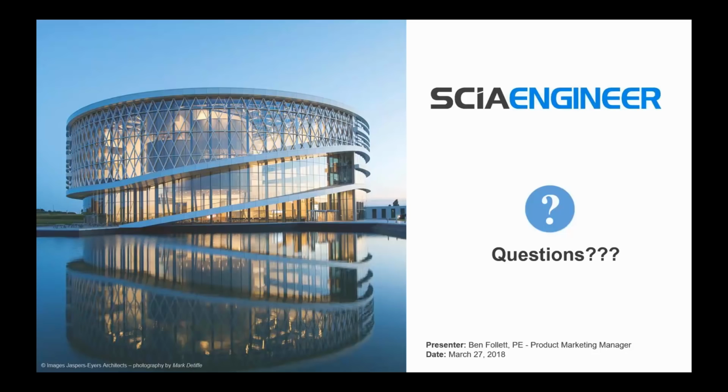Let's see what else. There are some questions about buckling. In this particular case, we have the 1D members that act as the stiffeners. Buckling is going to be defined based on where things are connected to those members. For the strong and the weak axis, we may have their total lengths, 25 feet being their unbraced length, but we could also evaluate that the shell that connects into them braces them in certain directions.